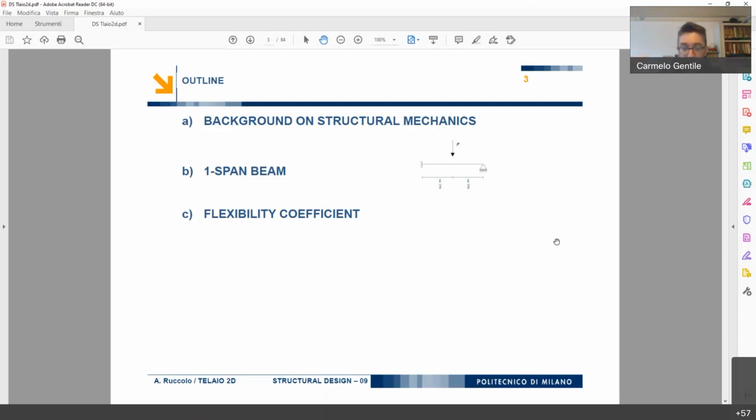Okay. If we see a free end with no load applied, for example, in Italian, una mensola a sbalzo, a cantilever, if we have no load applied at the end of the cantilever, we expect zero shear force, zero axial force, zero bending moment there. Okay, because there is nothing that can provide those forces.